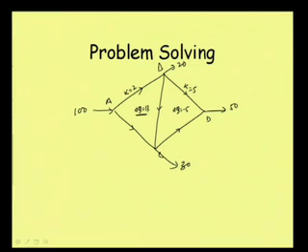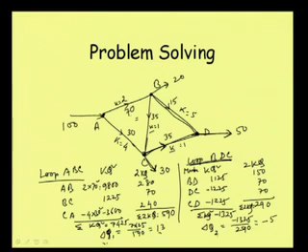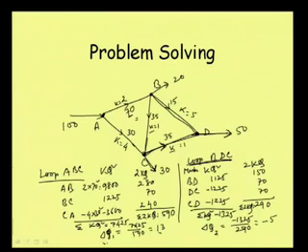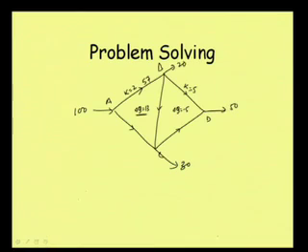So delta Q is equal to 13. If we just recall what our original assumed value was, it was 70. So this value will be 70 minus 13, and this value will now become 57. Then if we see this particular pipe, our first assumed value was 35. This is also clockwise. So from 35 we need to deduct 13.